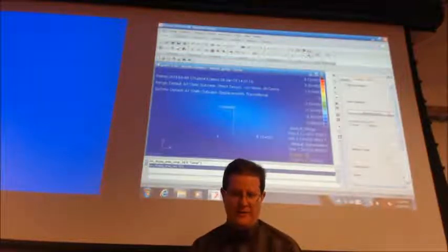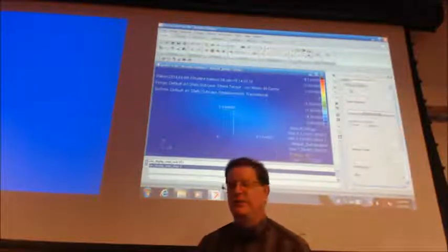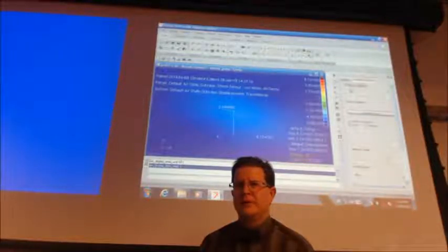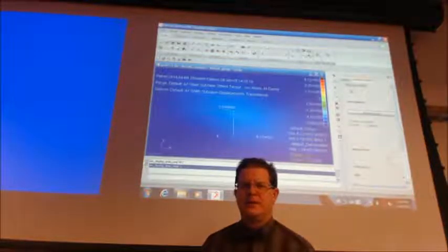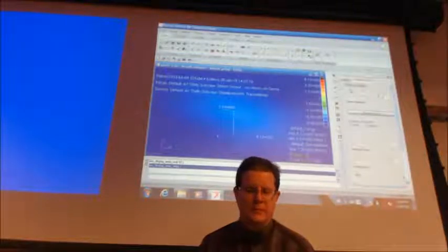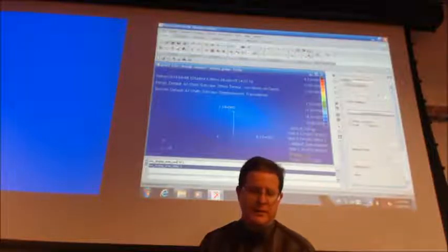So will our SolidWorks files go directly into this program? Yes. Well, you have to make them parasolids or X underscore B's. It's just a matter of how you save the file then? Yeah, you just have to export it in a format that Patran will pick up. Okay. That's what I did for this one.